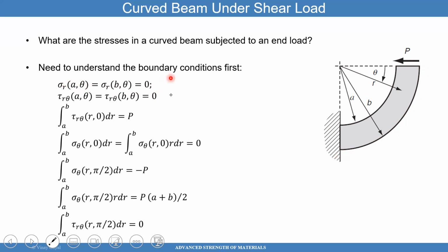That radial stress has to be 0 because I'm not applying any radial stress here. You can see here, there's no radial stress being applied. So that makes total sense. No radial tractions are applied. I'm not applying any internal pressure or external pressure. We also see that the tangential stresses at those two surfaces here and here are 0. We understand that too, because there are no traction loads applied on the outside surface or the inner surface. Any questions about those two boundary conditions before I move to the next boundary condition? It's very similar to what we did before.